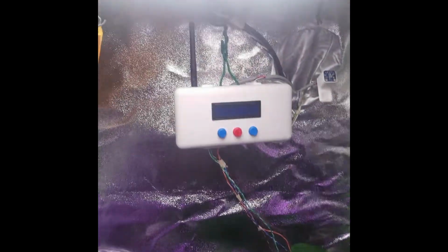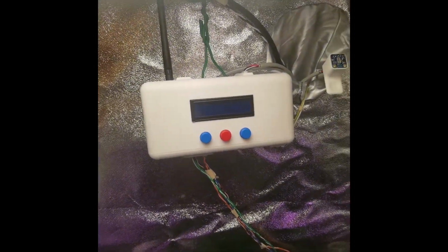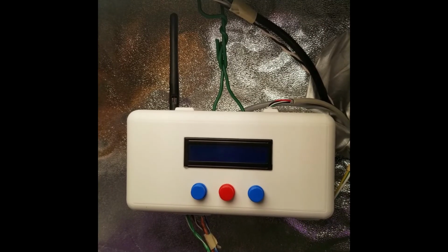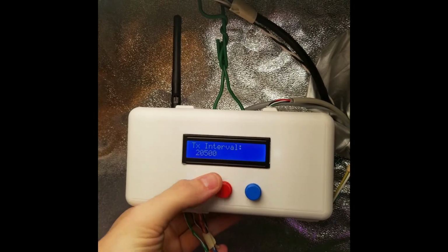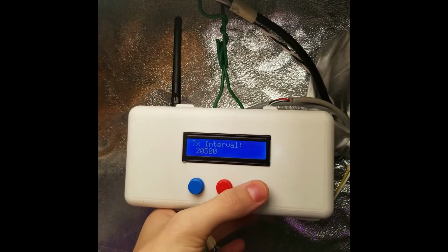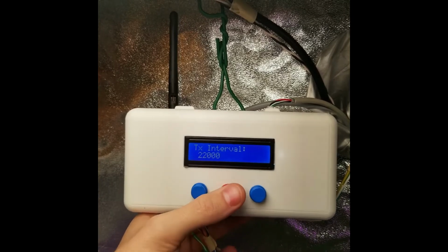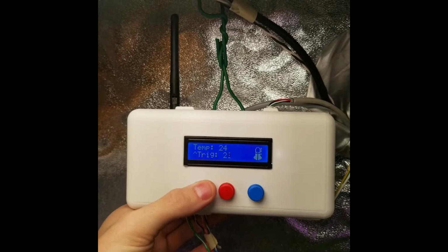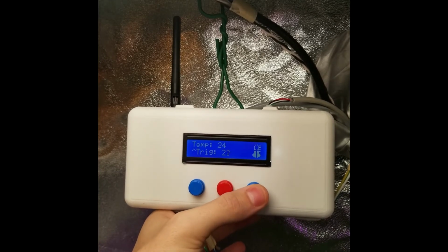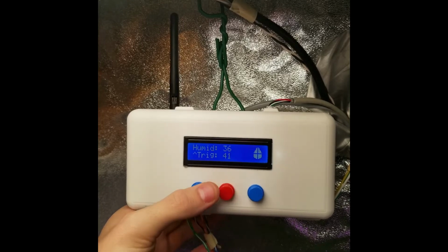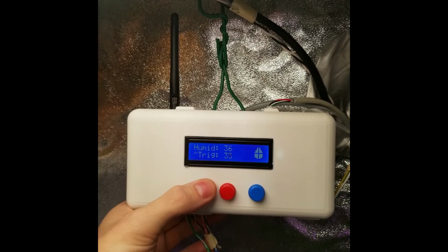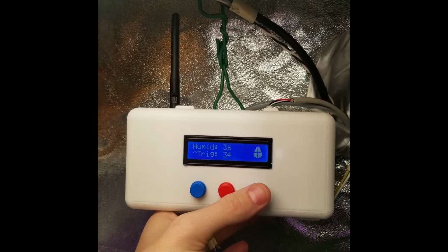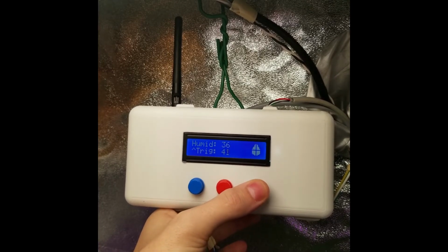So to demonstrate this module, I'll just zoom into the screen here. So you can see that there's an LCD and 3 push buttons. What this allows me to do is to adjust multiple variables such as the transmission interval, which changes in half-second intervals or 500 milliseconds, the upper trigger to the temperature relay, which you can see here, just triggering the fan in the corner here, you can hear it turn on, and you can hear it turn off. Same idea for humidity, follows the same principle, hear it turn on, nice loud fan, and hear it turn off.